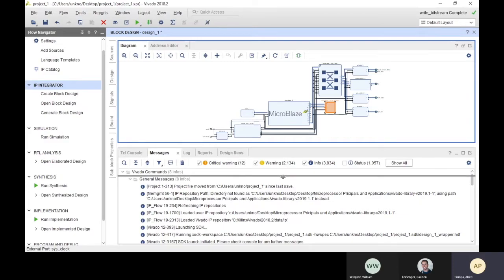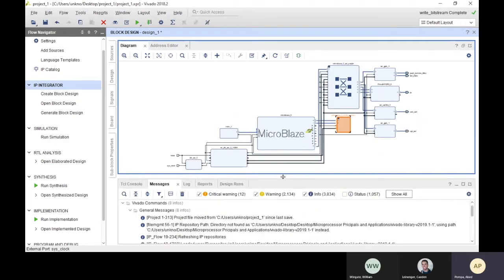which, as William explained before, when we tried to use Vivado 2020.1, we had nothing but problems. We could not get it to work with that design. But once we went to the 2018 version and went with the old SDK, which was used in 2018, everything seemed to work properly as it was supposed to. The new 2020 version uses a new SDK, which is called Vitis.